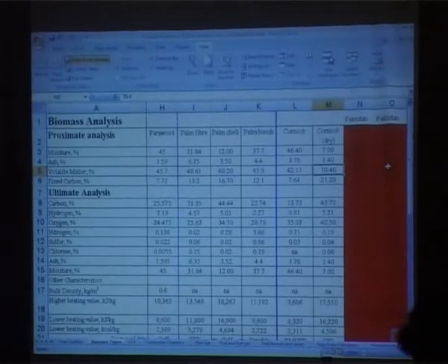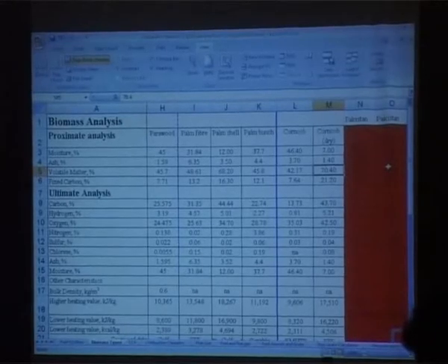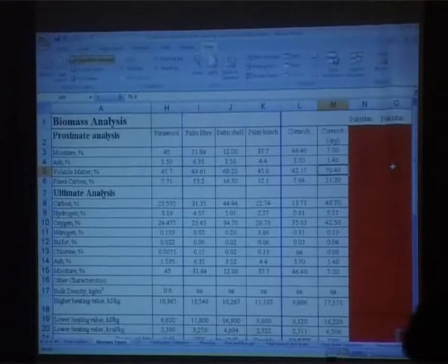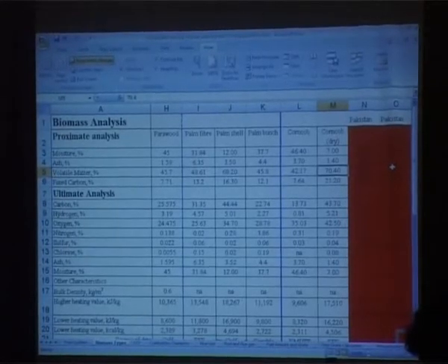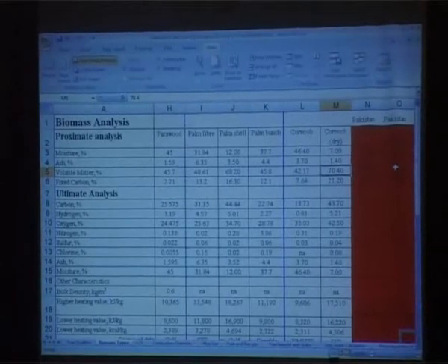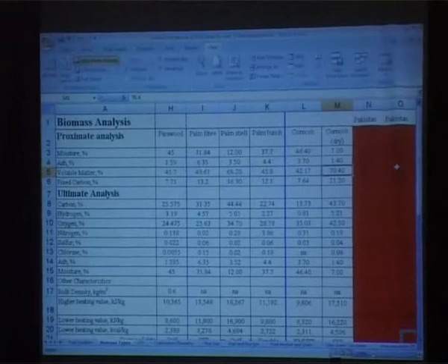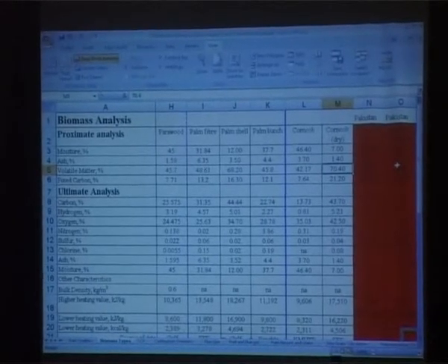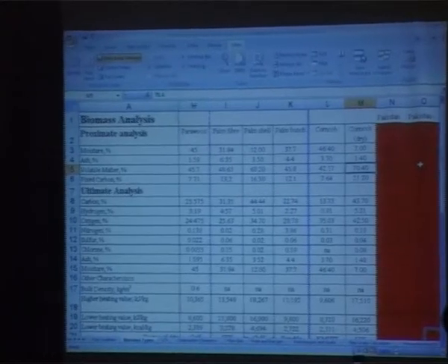If you have too low secondary air, you would probably start to have increasing carbon monoxide in the flue gas. And then you say, okay, I just put my forced draft fan, I give it higher revolutions, then you will increase your oxygen content in the flue gas, but your carbon monoxide will not come down. It's something with the balance between primary and secondary air.